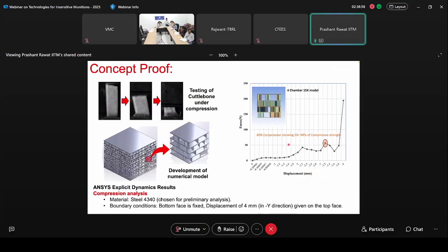After going through this particular investigation, what we have observed is that in our lab we have conducted compression loading at various strain rates, and once you compress it at various strain levels, we have observed the collapsibility up to 80% strain. This bone withstands or shows a constant value of the stresses that are being generated, or force values. I'll show it in the next slide.